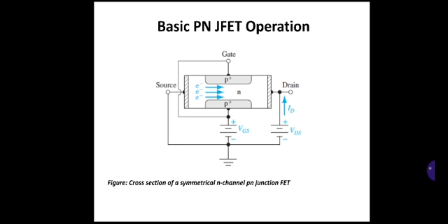So it is common practice to connect the two gate regions electrically. Therefore, the voltage VGS refers to the potential from each gate region to the source S. Since the conductivity of the heavily doped P plus region is high, we can assume that the potential is uniform throughout each gate. In the lightly doped channel material, the potential varies with position.